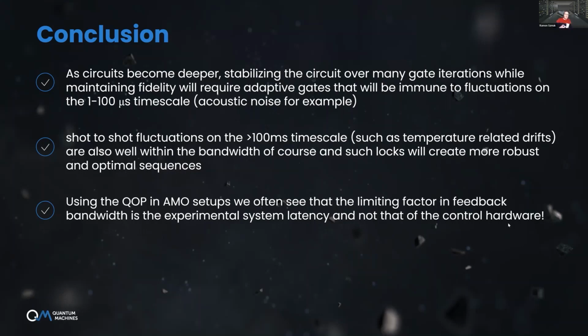Since the pulse is long enough, 10 microseconds, you can break it into parts. I've shown you that you can glue different parts with zero latency, with zero dead time. So you can break it into parts and have an interleaved PID loop that is optimizing the pulse as it's being played, to make an adaptive optimal control pulse for simulators.